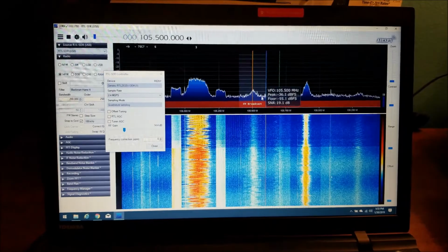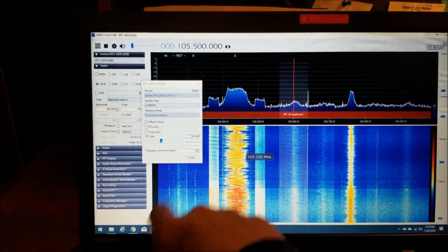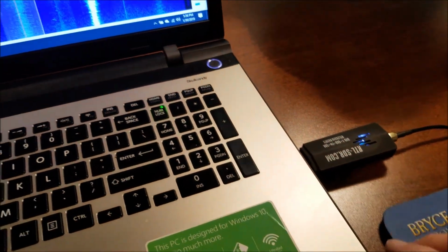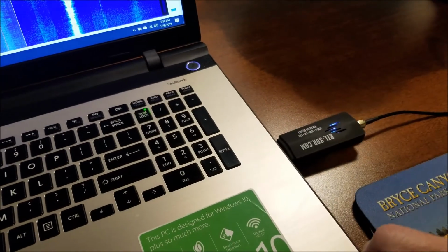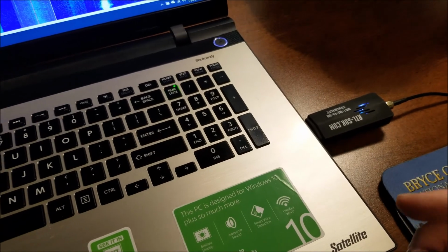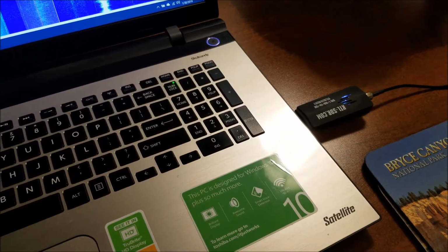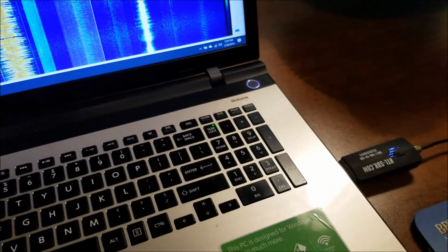And we'll go with that. We'll keep it there. And this is interesting. Frequency correction, PPM. On the dongles, or pretty much any type of transmitting or receiving device that's based off of frequencies, the electronic circuitry needs a baseline frequency so it can adjust to a frequency that you want it to listen to, etc.